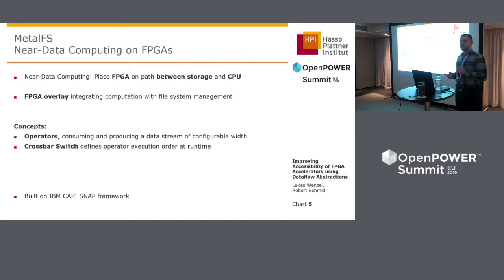The basic idea is focusing on near data computing, actually because we have an FPGA card that features 2 terabytes of NVMe storage, which makes it very interesting to explore these kind of workloads. And well, as you might imagine, we just have an FPGA on the path between the CPU, which communicates with the FPGA via CAPI 1 in this case, because it's quite an old card. And on the other side, we have just the FPGA communicating with the NVMe storage blocks.